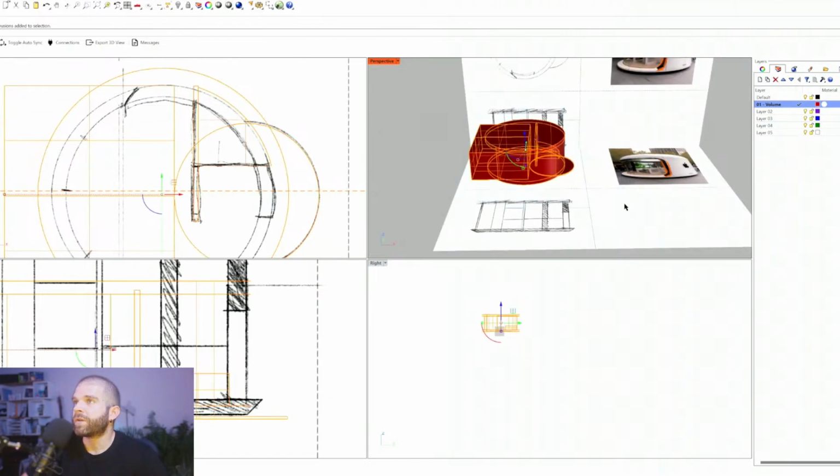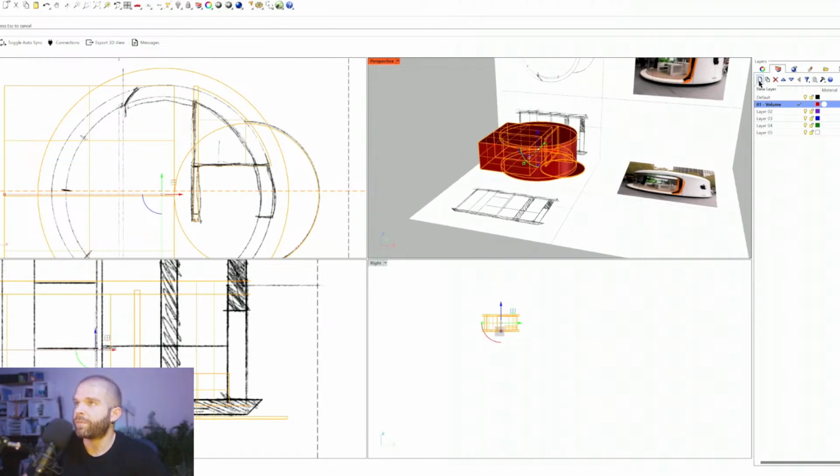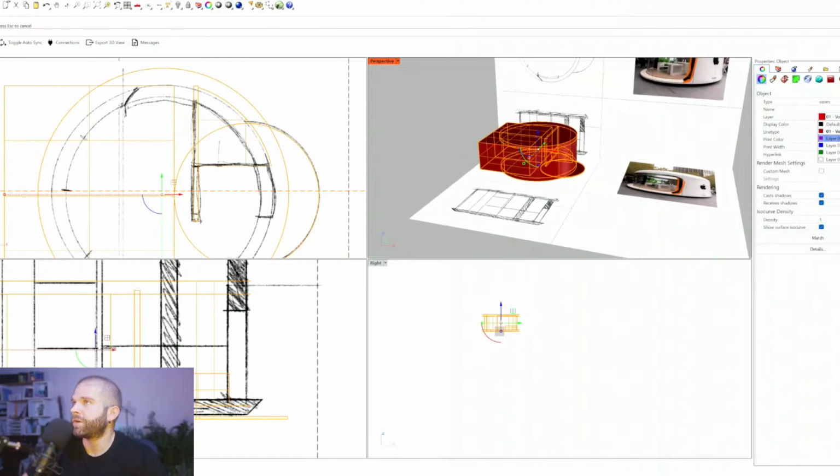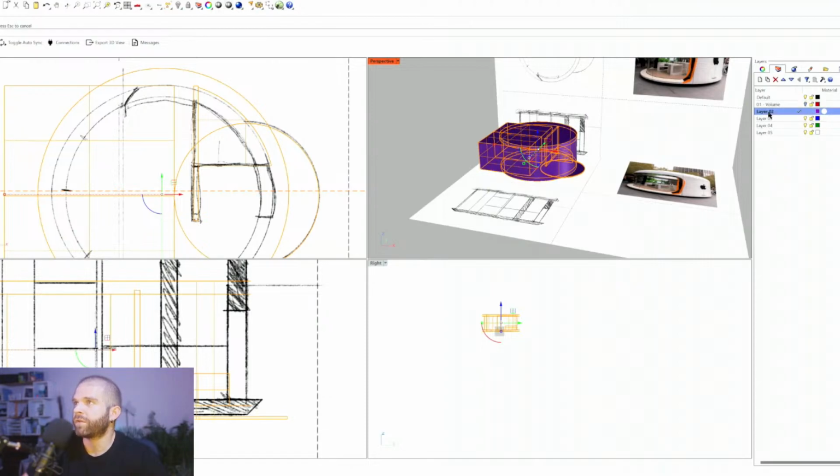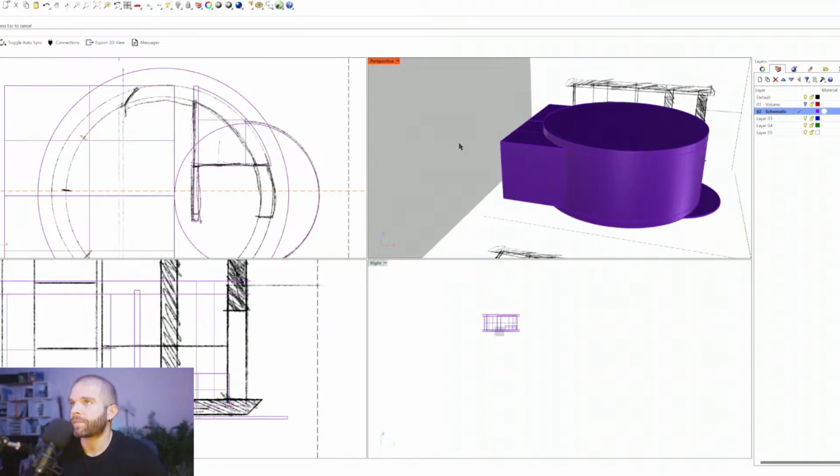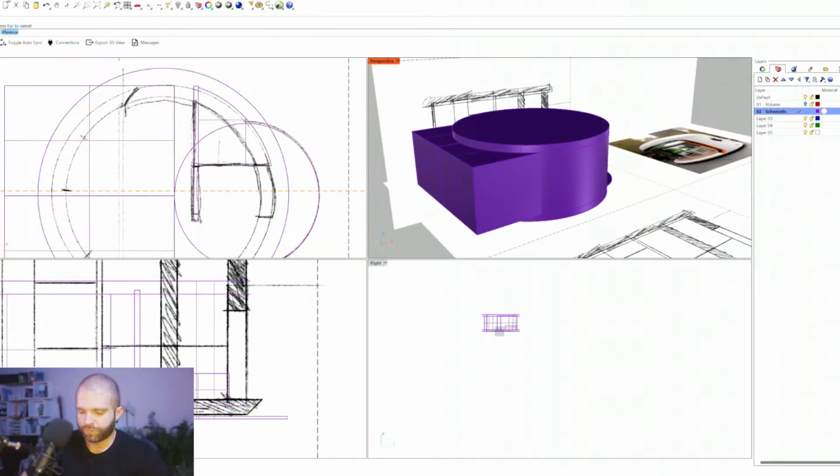All right, so similar to the sketch, we had our volumes and we've got our areas all set up. Now I'm gonna select all this stuff, copy, paste it, and change it all into layer 2 so that I can always refer back to my volumes in layer 1. So now everything goes purple, and we'll call this our schematic. Yeah, that's fine. So we can do Boolean difference. Subtract from. So we're going to subtract from everything, kind of.